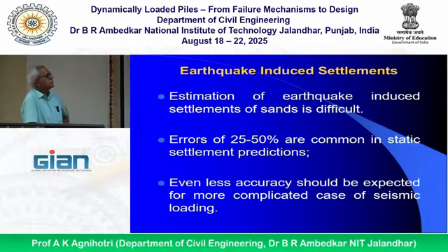Now, estimation of earthquake-induced settlements of sands is difficult. Errors of 25 to 50% are common in static settlement predictions. So even less accuracy should be expected for the more complicated case of seismic loading. So settlement calculation definitely will have great errors.